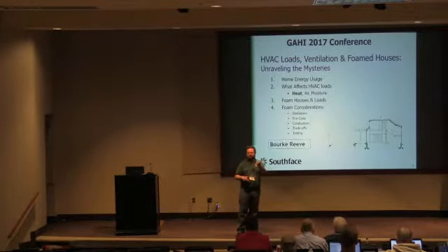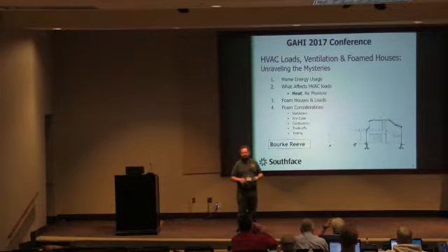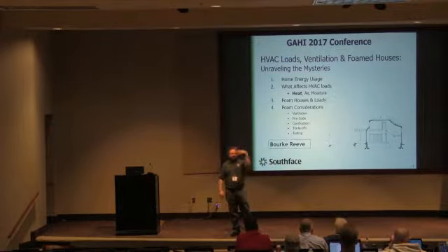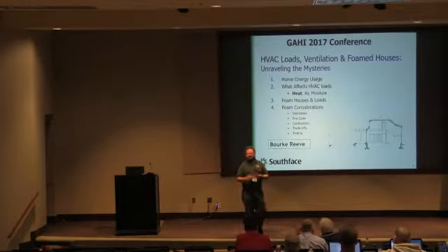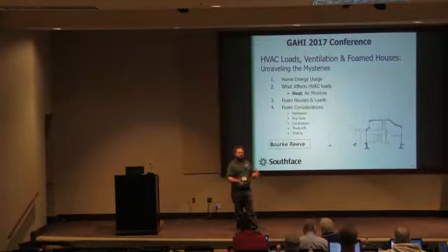You're changing the thermal envelope. That means you've got a different system that your house is operating under, and that's going to have different considerations for how you heat the house, what type of furnace you put in there, and the ventilation you have to bring into the home. They were replacing their duct system, moving it from a crawl space into that foamed attic, and I told her you really need to do a load calculation, right? Because you've changed how the house works, and you're moving the system from a crawl space into an attic, but into a sealed attic rather than a vented attic. So this is something that we see all the time in the real world.